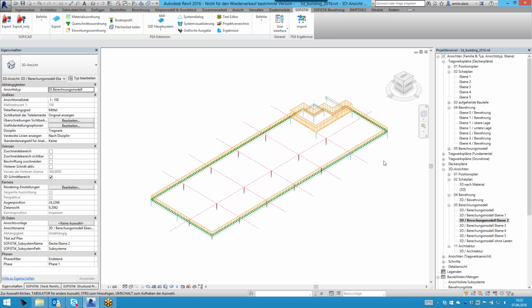So first is that we have some variable load. So this is this highlighted load now on my screen. So this is a variable load on the entire slab, and normally structural engineers like to create some load patterning, to divide some loads, to have loads on each single span, to get a minimum maximum envelope of bending moments and shear stresses and so on.